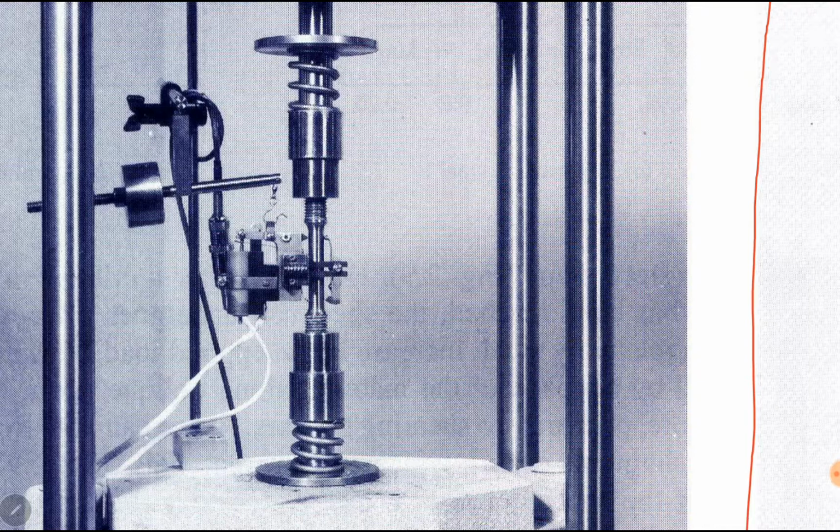And deflection at E is a geometric deflection. We will find it after we find delta B, delta D. So we have to find how much this portion E has shifted below. We have to find it geometrically, because BDE is a rigid member, so there is no deformation in it, but there is a rotation in the member, so E will move from its position.